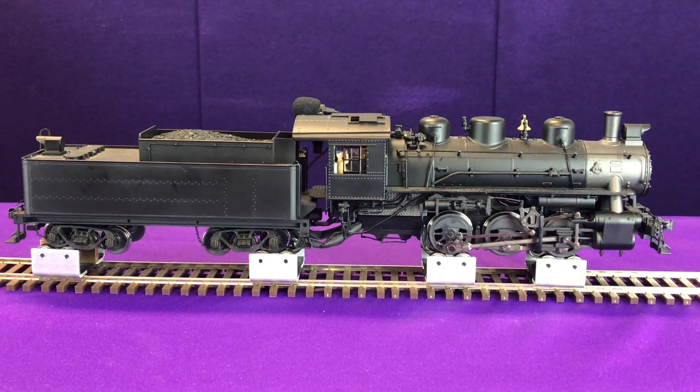So when I press the F5, what it's going to do is shorten the amount of time the valve is applying steam into the chest. So when I push the F5 button, you kind of hear that chuff change. Now I'm going to turn on the F5 again.